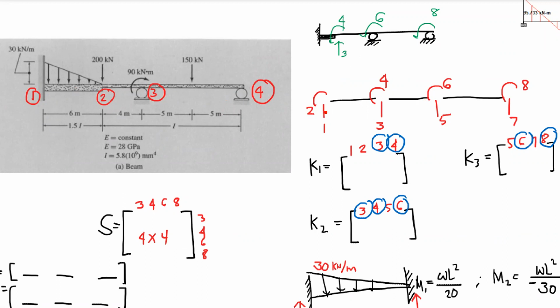Similar to finite element, as I've always said, matrix analysis is already part of the finite element concept, because we're basically subdividing the problem into each member, depending on your discretion as a designer, as an engineer. Here, it's my discretion to put in a node here in 2 because there's a change in inertia.